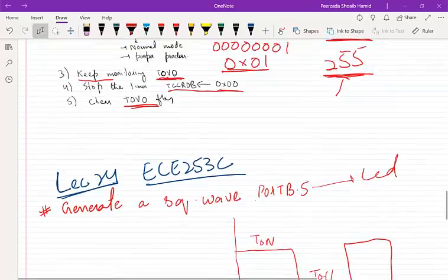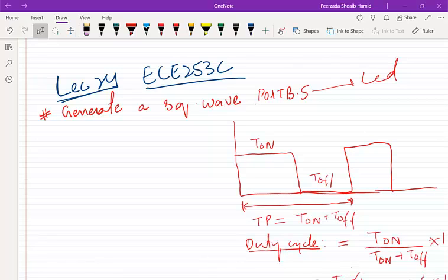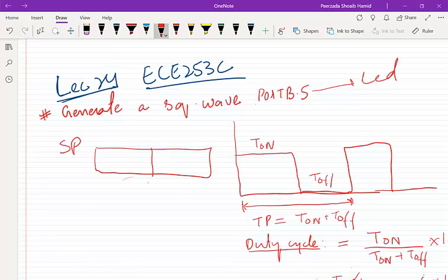These are our 5 steps, but before that you should know that, as we have already discussed, if we want to use a subroutine in our program, we need to initialize the RAM. And how do we initialize the RAM? We actually need to put some values in stack pointer high and stack pointer low, because the stack pointer is a register that always points to the top of the stack, and it's a 16-bit register. The registers are referred to as stack pointer low and stack pointer high. So first we need the last value of the RAM, so that we start with the last value. We have discussed this in our previous class.